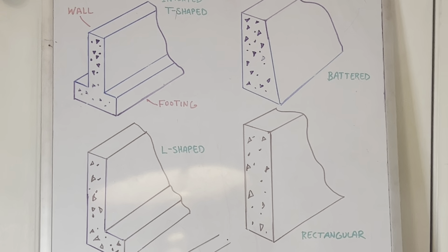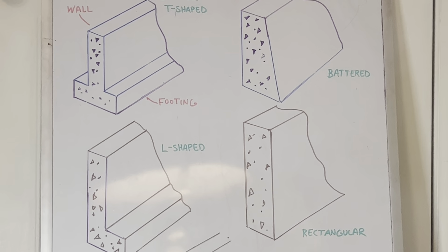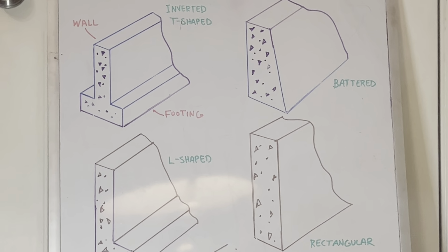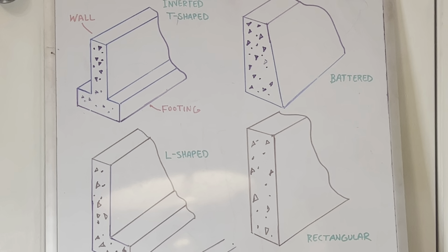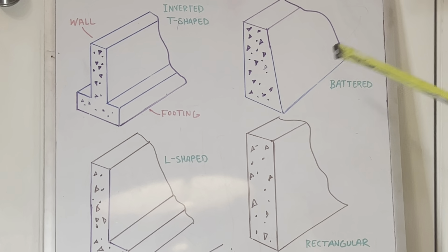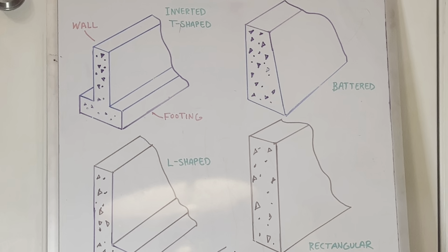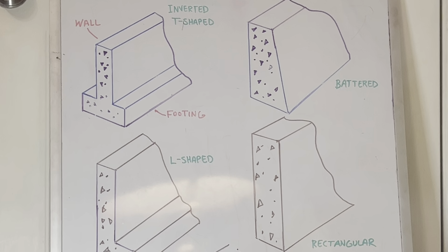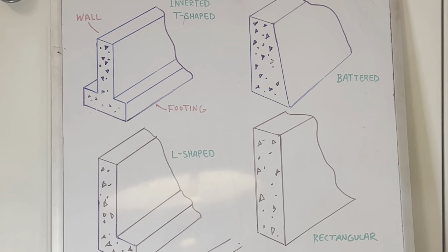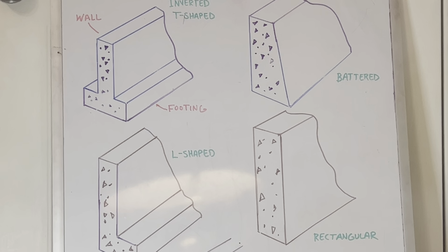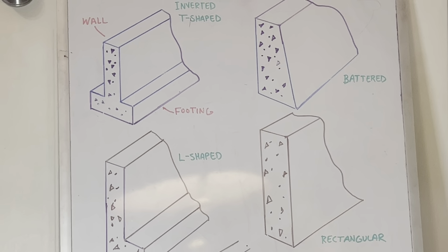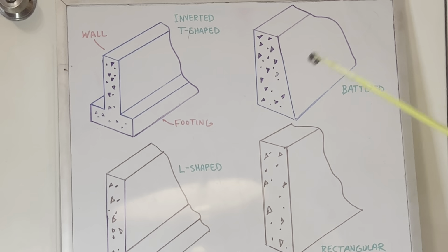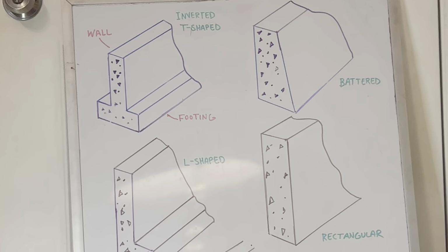You might have a lolly column or wood posts. Those wood posts are going to be sitting on either a battered footing, something like this. You can buy some footings from your local home improvement center. It's already made. Or it's going to be sitting on some type of concrete footing or pier to support that interior load-bearing wall.